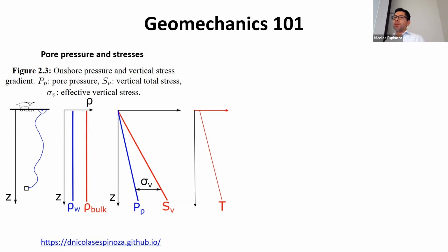I see that many of you are familiar with this. I don't know if you also know the variations of horizontal stresses with depth, which is what just popped up there on the screen. These stresses are very important because horizontal stresses are going to tell us in which direction hydraulic fractures are going to propagate. They're going to tell us in which direction we need to drill our horizontal wellbores, and they also control which type and orientation of fractures are going to reactivate in the subsurface.